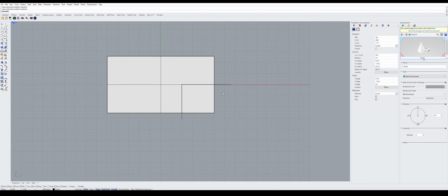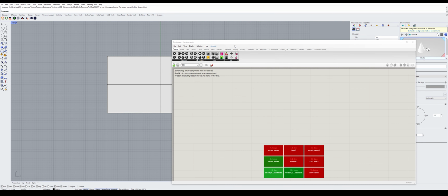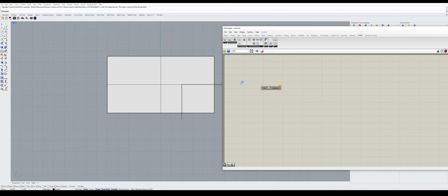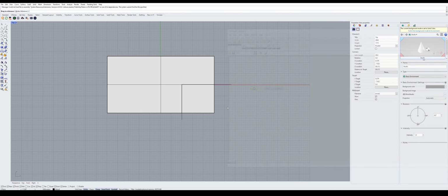Open up Grasshopper. We have a blank canvas here. Go to our Ameba 2 ribbon. On top of the Ameba 2 ribbon, we select Ameba Geo in order to capture our geometry. Type Prim. Connect our component and set our component to the surface that we created.